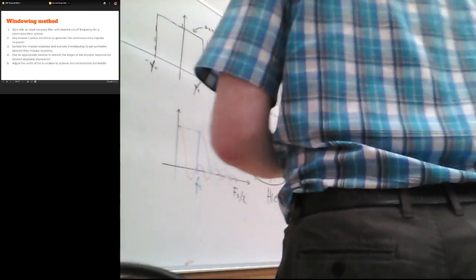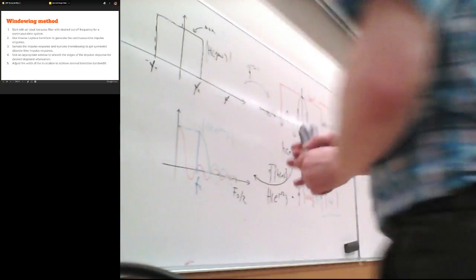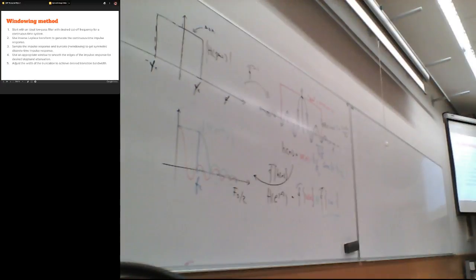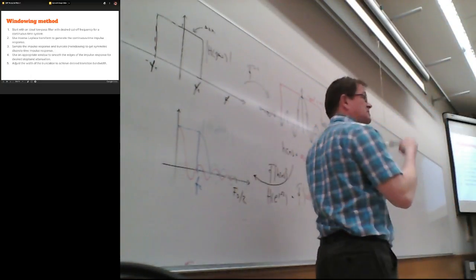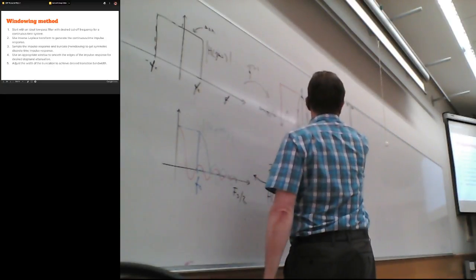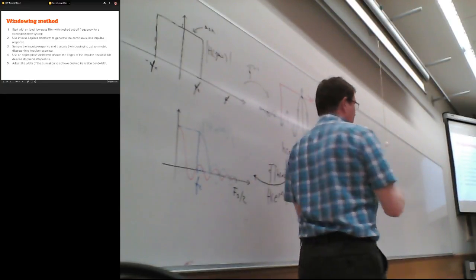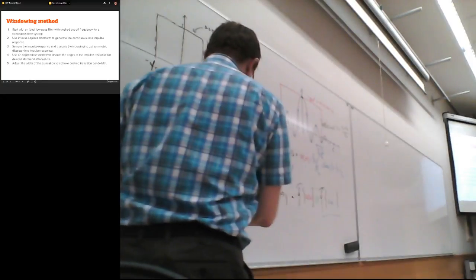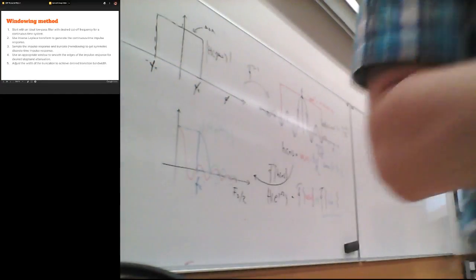Okay, good. But that's the start. We can actually next go and try if we get a proper control over the cutoff frequency. Since, yes, with this method, compared to, for example, the running average, which is simple box window, we can actually control the cutoff frequency of the design.